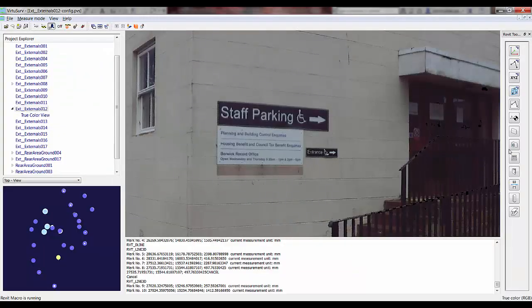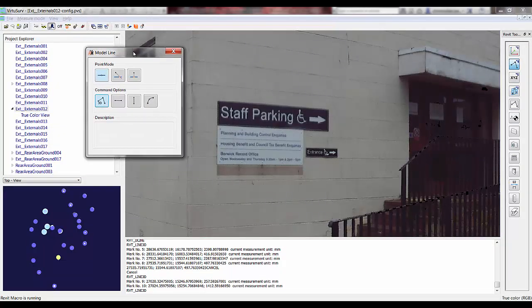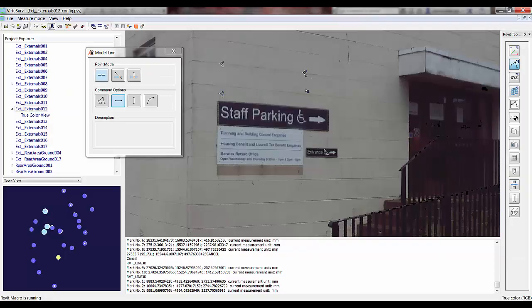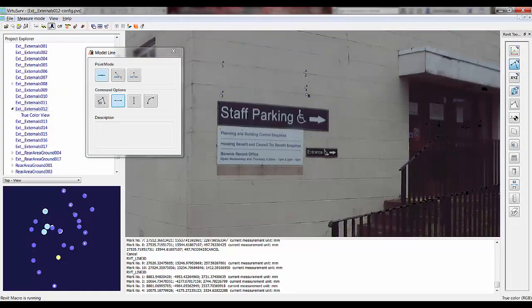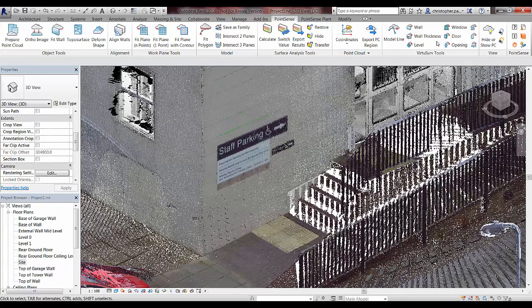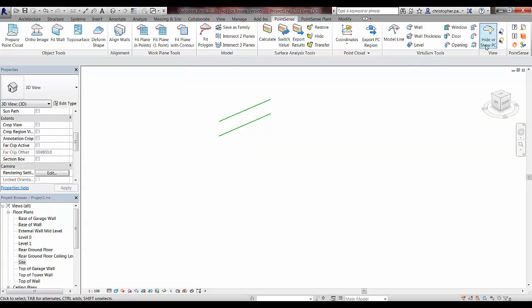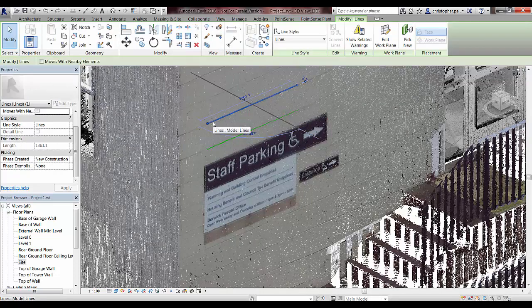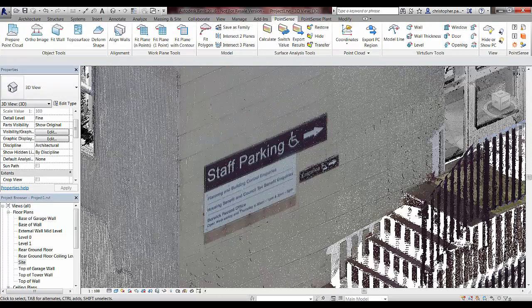you'll notice that when we select some points with the horizontal model line, it will average the Z value to give us a nice clean horizontal line. So if I just take 2 picks here along this mortar course, and I do a similar application just below this and take 2 different picks, it'll average the Z value between those 2 points to give us a straight line in a horizontal plane. So you can see we've got a very similar result from 2 very different selections there. So let's delete those off.